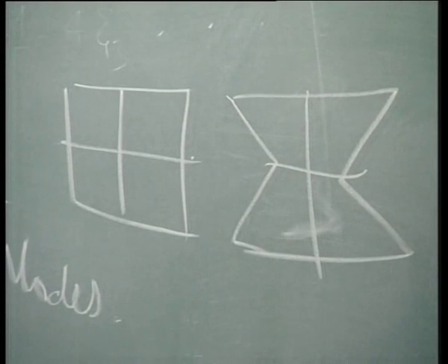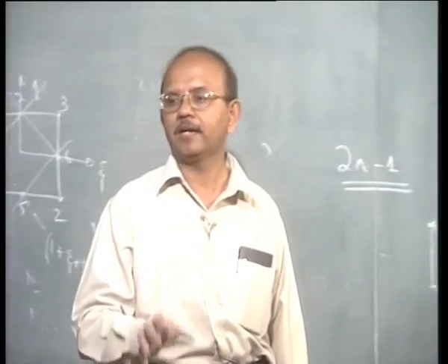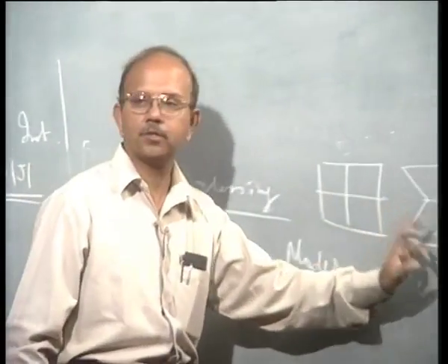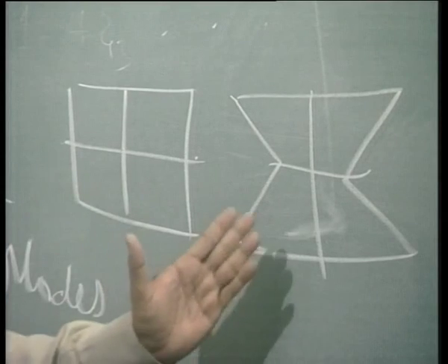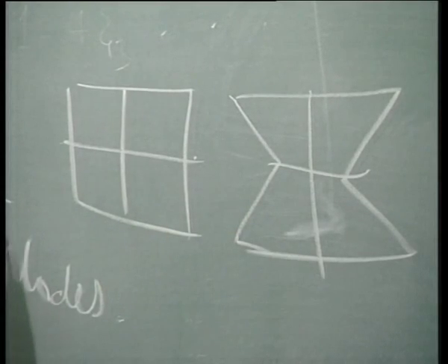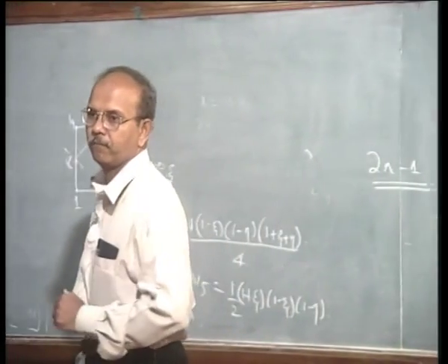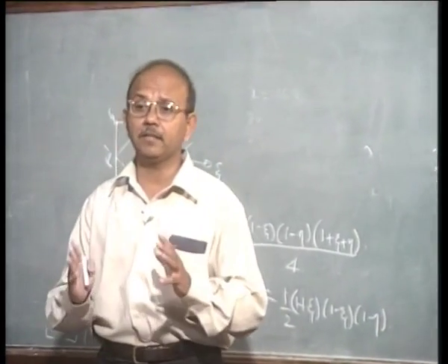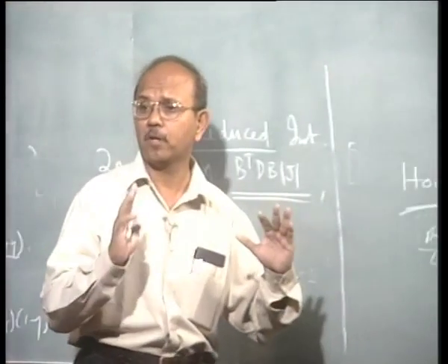Okay, the jagged front gives some sort of an impression that an hourglassing is produced. Hence we call this an hourglass mode. What do we mean by zero energy modes? Please understand that they are very important. Let me just recapitulate what I am trying to say.